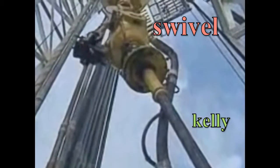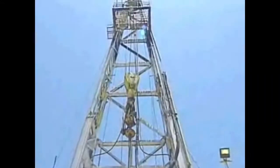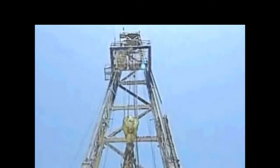As I said before, the top of the Kelly is attached to a device called the swivel. Allowing the Kelly to rotate, the swivel provides a passage for the drilling fluid to flow from the surface to the bit below, and also prevents the traveling block and hook from rotating while the drill stem is being turned.